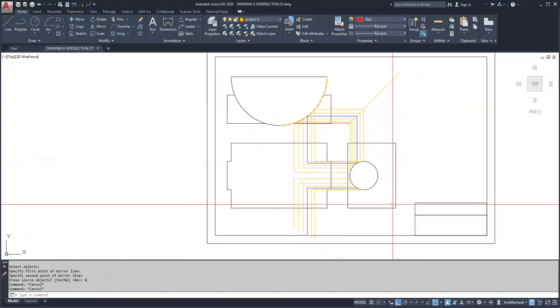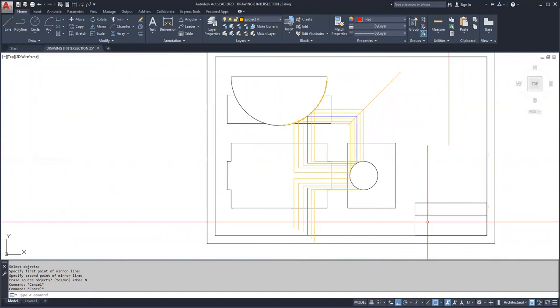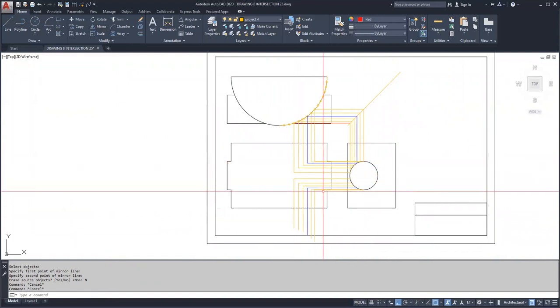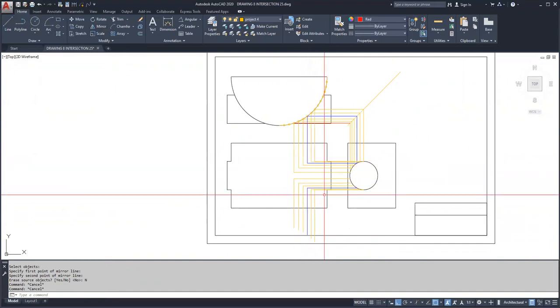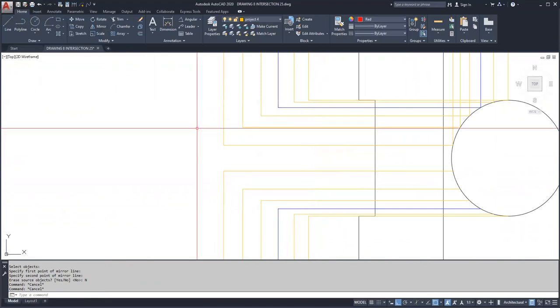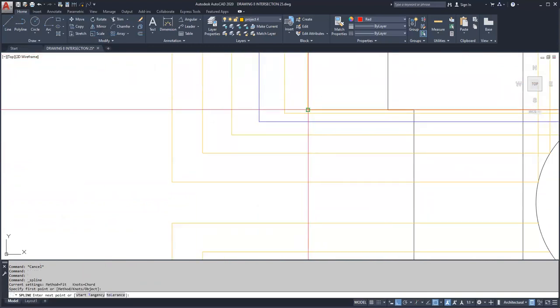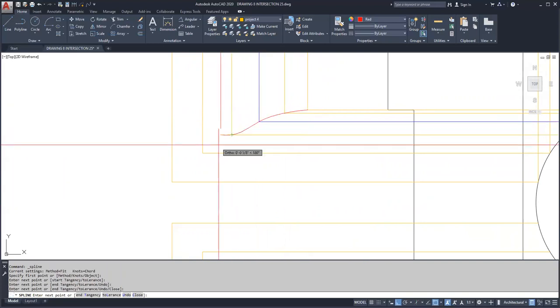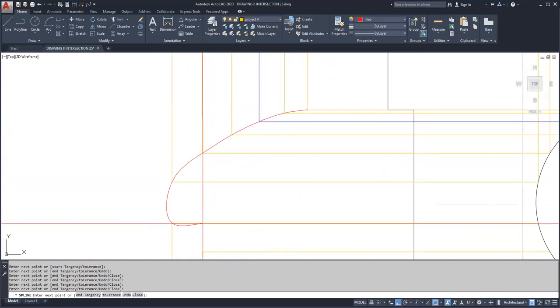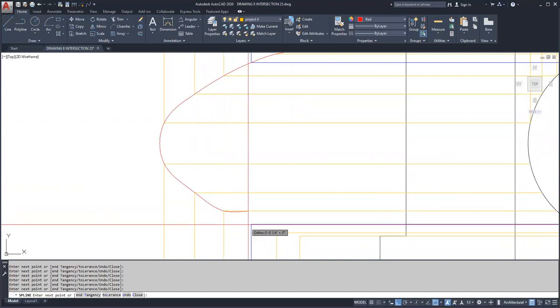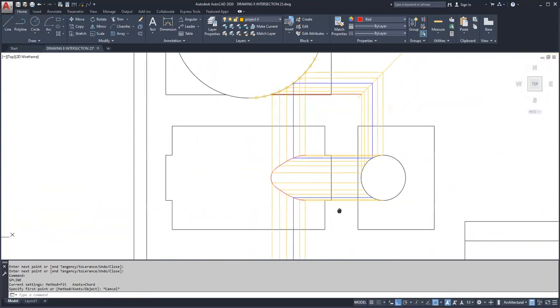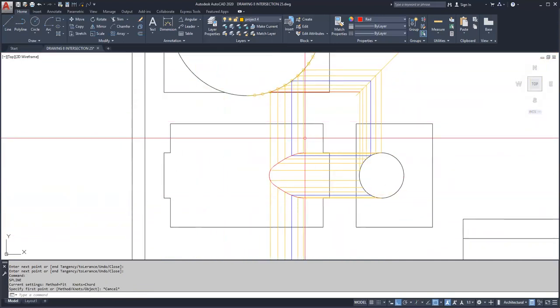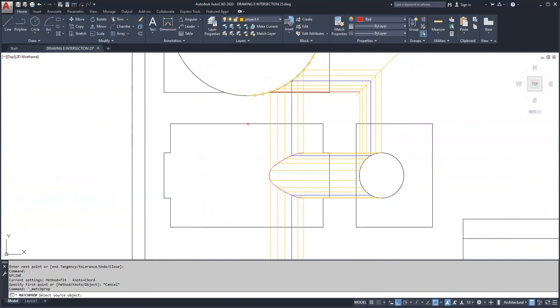So what did I do now? All I really did was create a bunch of points for me to use a spline. That's a tool in AutoCAD to create an arc. Drawing it by hand, you would use a French curve. Or that tool that we call Gumby. And you're going to get an object that looks like that. Let me color that solid.